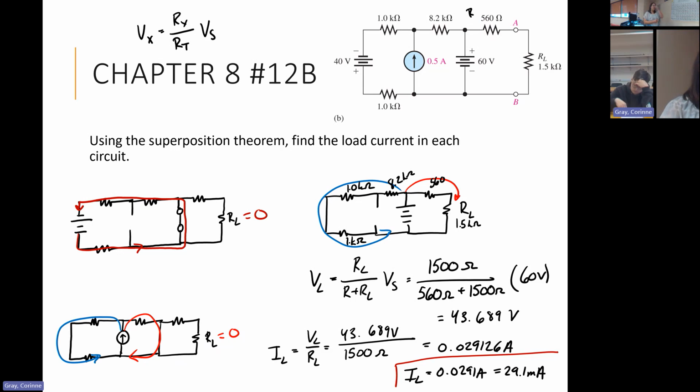Would you need to convert it all? Typically, if you had internal resistance for one of your sources, one of the things you can do is convert them all to the same type of source and then go through a new superposition. With the two other methods we're going to talk about, they have ways of getting around that as well. So you might not want superposition explicitly for one of those. Okay. Any questions about superposition?